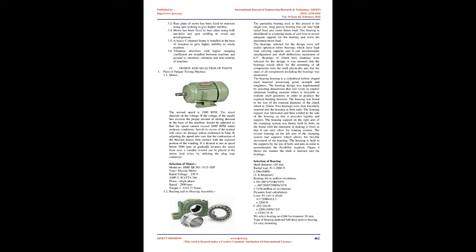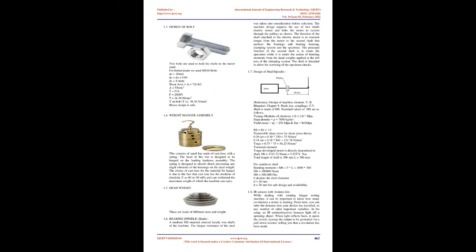The shaft ID is threaded to allow for screwing of the specimen chucks, giving higher alignment between driving and driven shaft and drill chuck. The optimized length of both shafts was selected and machined accordingly. The base plate of the motor has been fixed to the structure using spot welding to give higher stability. The motor has been fixed to the base plate using both nut bolts and spot welding to avoid any misalignment.